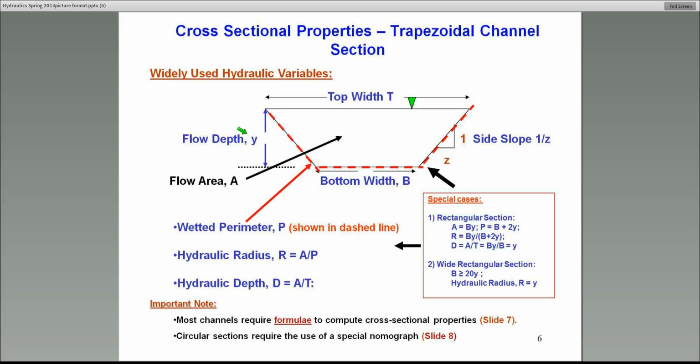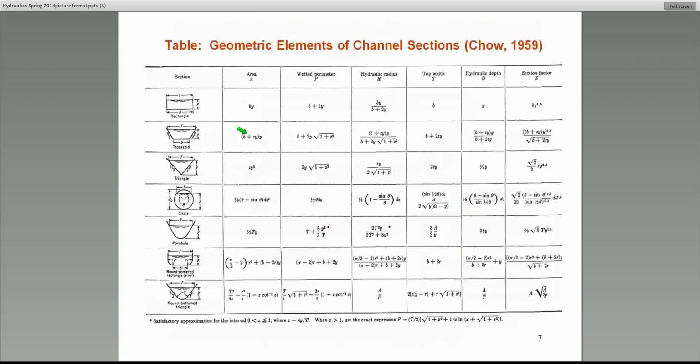In a full pipe flow, the cross-sectional area is fixed, and therefore that makes it computationally a lot easier to deal with a full pressurized circular pipe than to deal with an open channel system. Okay, and that's why we have two different types of hydraulic situations with these two systems.